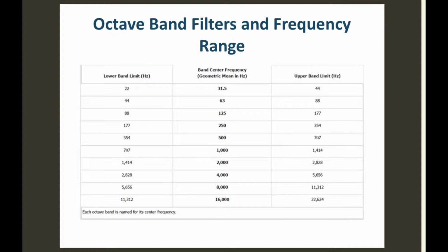So when you look at an octave band analyzer, you may not see 22 to 44 hertz as the lowest band, right, in the lowest octave. What you'll see is the midpoint, 31.5. And the next one is 63, but it's really a range around 63. Next one's 125.